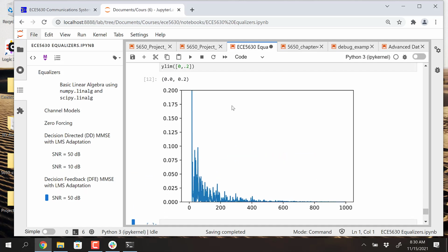This would be like the learning curve in a machine learning application where it's learning where it needs to go. So it's trying to drive to the bottom of the bowl in the LMS algorithm. So that's what it's doing. If I put noise in the system, it doesn't look nearly as nice as that. It stays chaotic because the noise is in there. But with a noise-free case, this looks pretty good. If mu was too big, what would happen is out in here and beyond, it would start coming back up again. It should go down and converge, and it should not go unstable. But if it's unstable, then that's what will happen.